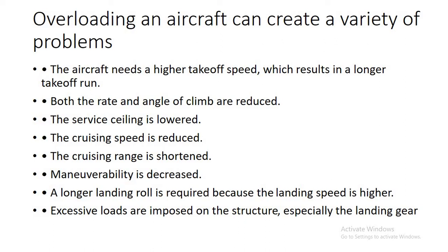Then your controllability and maneuverability of the aircraft will get reduced. And while landing the aircraft, your landing roll will become longer. That's also another disadvantage. Then if your weight is too much, then there will be a lot of unnecessary excessive loads being imposed on the structure of the aircraft.